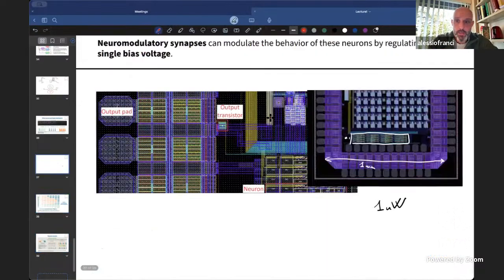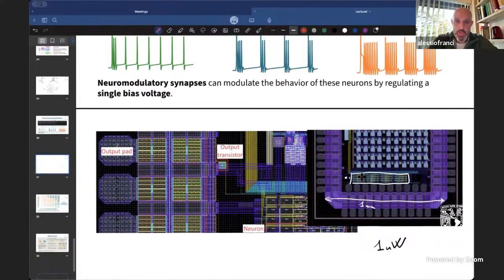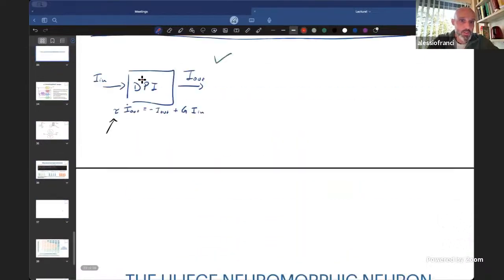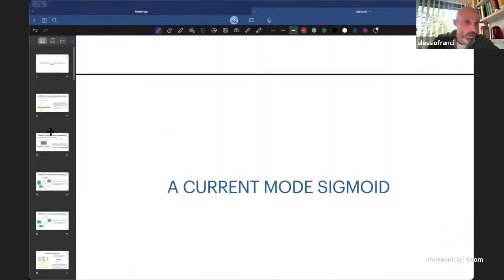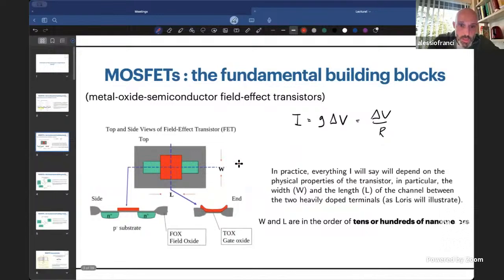When you design a chip, what you're doing is literally telling the foundry, let me go back to this drawing here, I want this width W to be, for example, 0.5 micrometer, and length L should be, say, 1 micrometer.